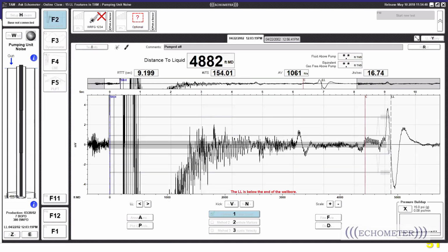I hope that clarifies Lupe's question. So when do you want to stop the test? Well, when you feel comfortable with the pressure buildup and it's actually representative, it's not jumping all over the place. Having this jumpy pressure might be due to a leak on the wellhead, on the connections, on the gun, or due to an out of calibration pressure transducer. Might be several reasons.